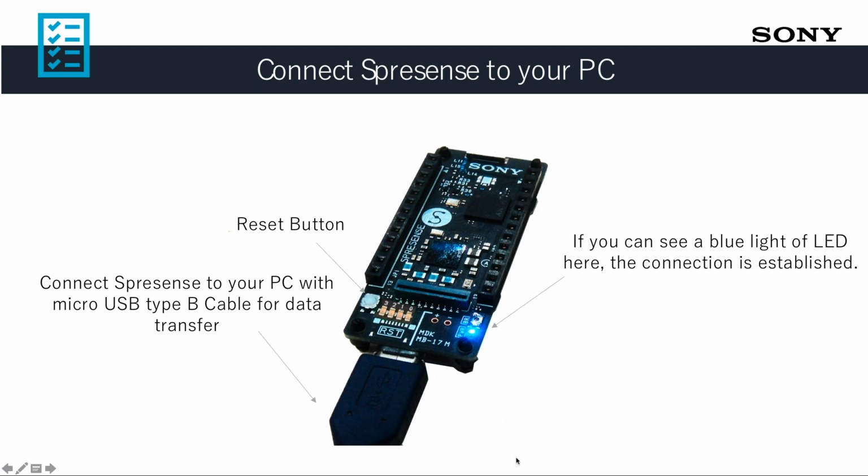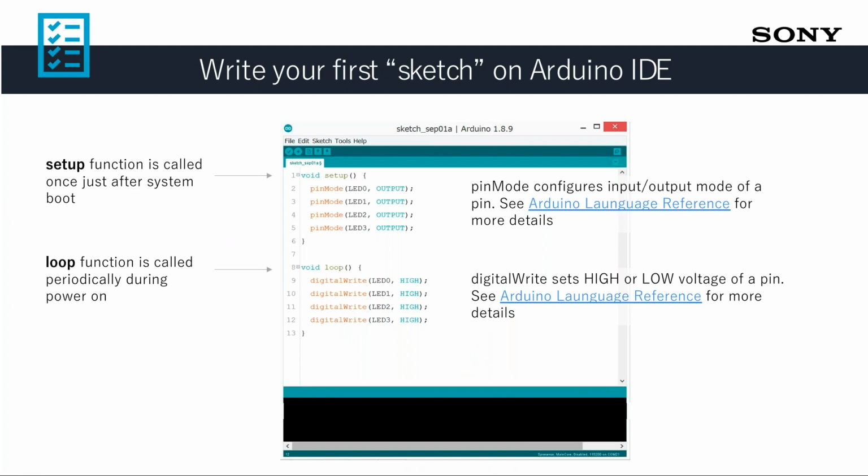And now let's write our first program, right? So to write our first program, this is very simple. Spresense has 4 LEDs already integrated on the board. And then you can address those LEDs, you can turn them on and off, and you can use this feature for testing, debugging, and so many other things, and make sure your board is all connected. So this program is very simple, it is accessing LEDs 0 to 3. So you can see LED 0, LED 1, LED 2, LED 3.